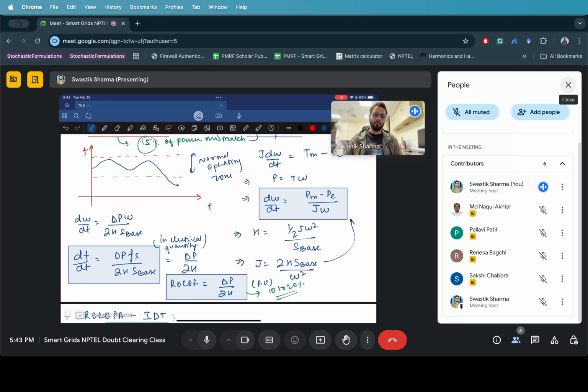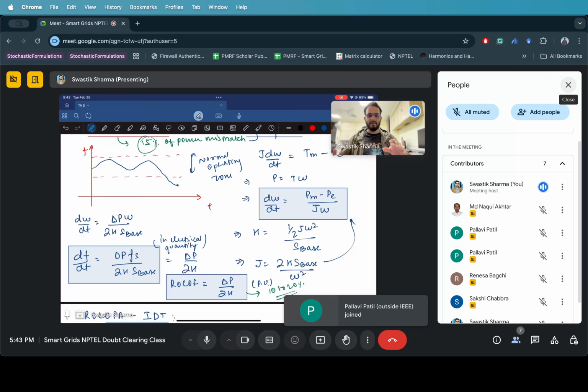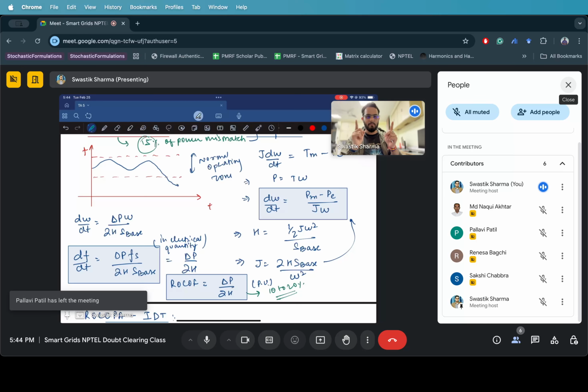I'll touch upon this when microgrids are discussed during week 7 and week 8, but still, I'll give you a brief overview. There is a concept of virtual inertia. In virtual inertia, instead of operating solar PV panels at their maximum MPP point, we derate them and operate them with a certain headroom. Let's say they are able to give some P max, but we operate them at some P bar level so that there is headroom available, and we can ramp up our generation when needed.